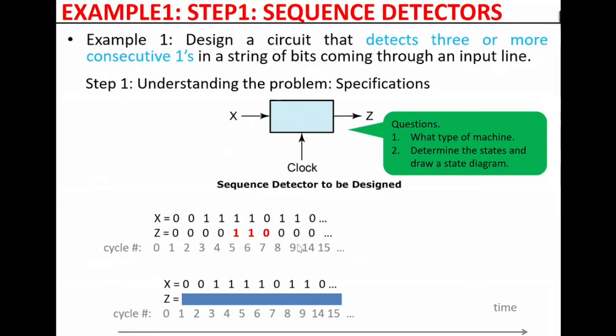What machine is that? The Mealy response. Immediately the input changes, it responds. Mfundo, you are right. You will see 1 for the Moore, and you will see the difference. One is faster than the other. The other one is slower. The Mealy, immediately the input changes, it reacts to it. The Moore doesn't. It reacts to the state.